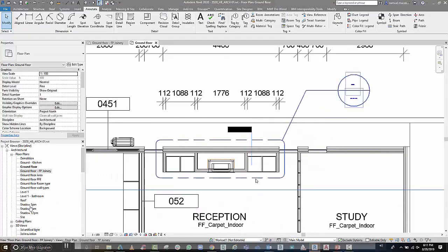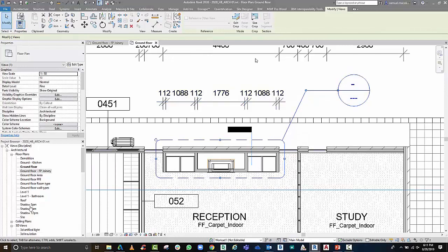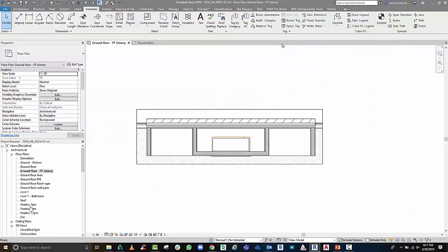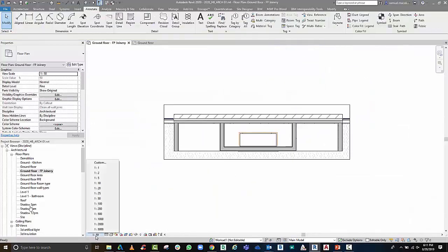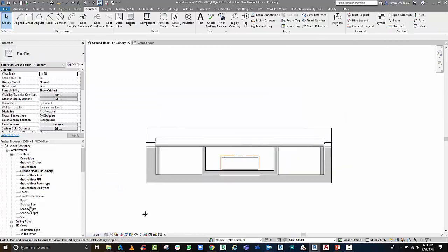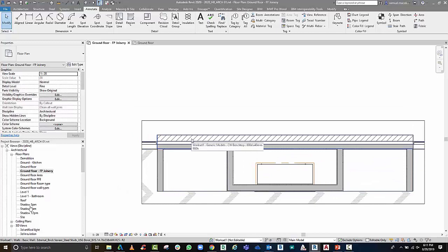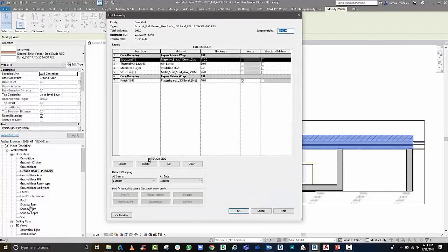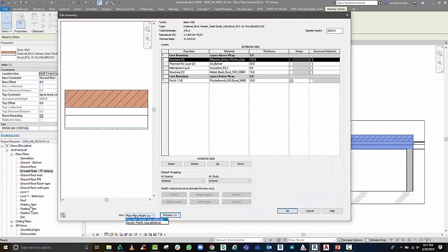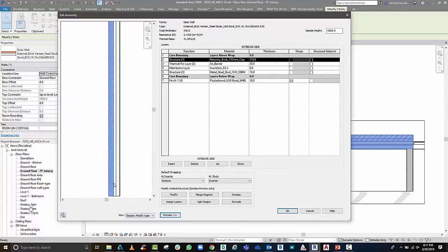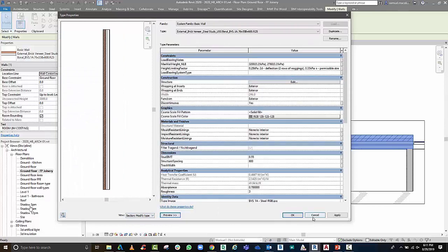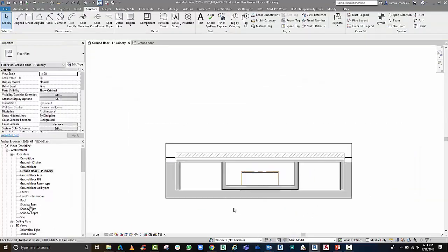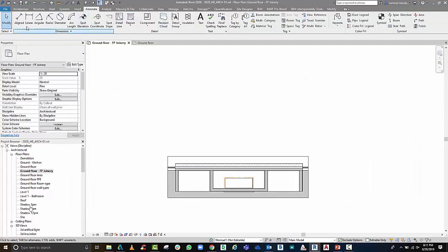So what we have here is a call out. Basically, we can go to any part of the model and draw a shape around it and then do a call out to another view or to another more detailed view, which we can start to adjust and scale. So I just changed the scale from 150 to 120, and there's going to be more detail showing up here. So as we go in to look at maybe the more detailed information of that wall at 1 to 20, it's been revealed because we've done this call out and we've changed the view and we've changed the way it's going to display.